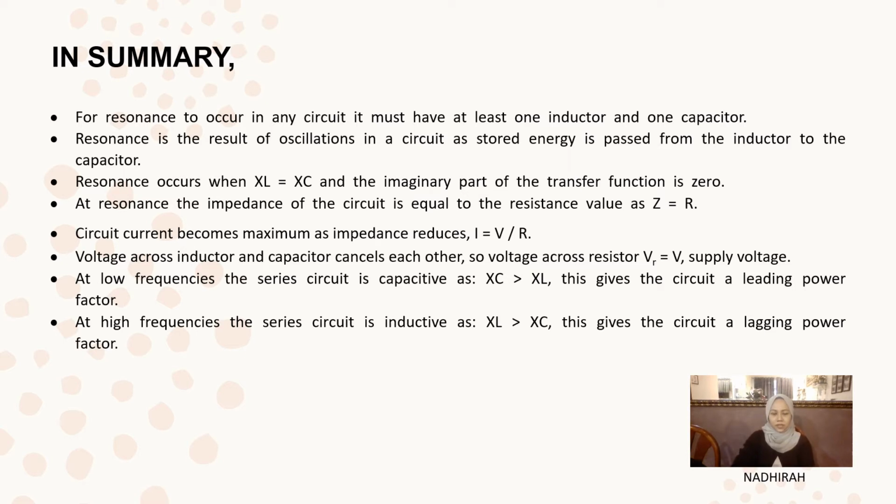At low frequencies, the series circuit is capacitive as XC is bigger than XL. That gives the circuit a leading power factor, while at high frequencies, the series circuit is inductive as XL is bigger than XC. This gives the circuit a lagging power factor.